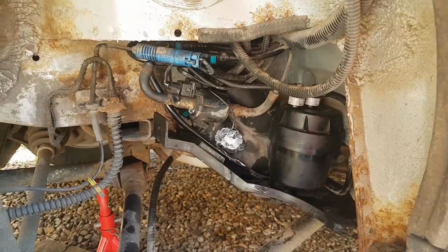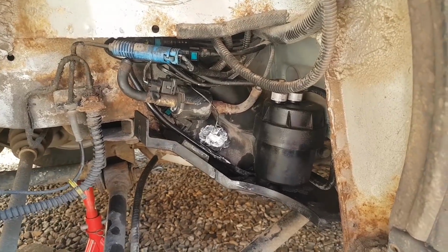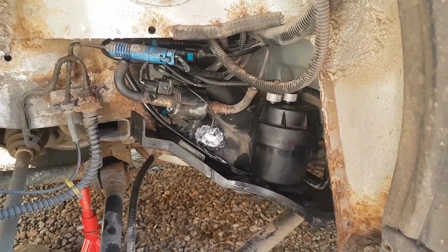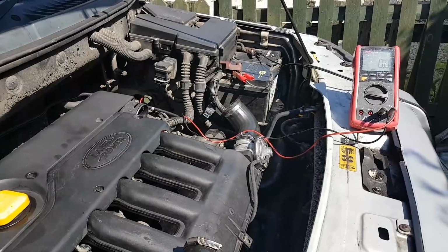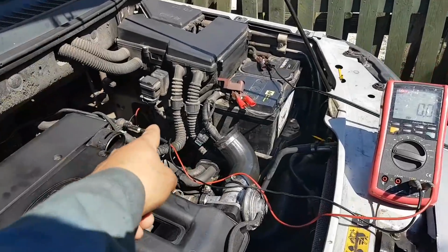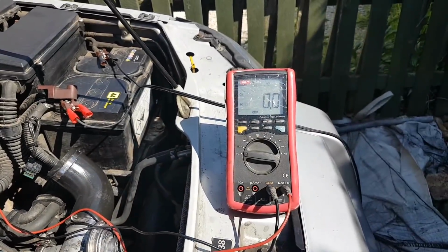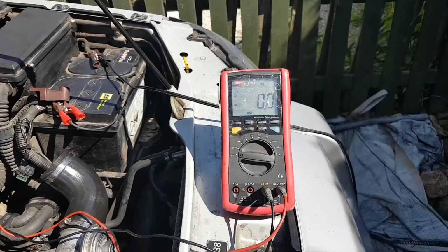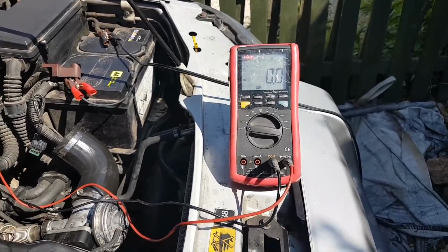And I think we are pretty much ready to try. Even before finishing off, we can just turn the ignition on and see which pressure we get now. Okay, and the first thing we're going to check is the voltage signal at the sensor. If you remember, it was about 3.1 volts, something like that. And that was when we had the car running okay.